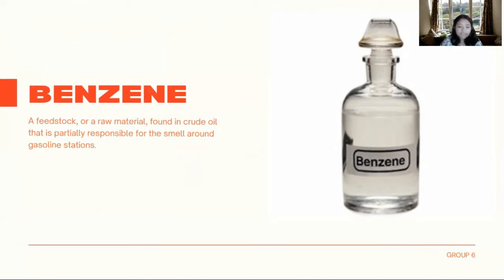It is a colorless and flammable liquid that is used as a gasoline additive since it increases the octane rating and decreases the spark knocking in gasolines. Benzene is considered, however, as a carcinogen. That is why it is typically fully reacted in a closed system wherein only up to 0.62% benzene content remains in finished gasoline or petroleum products.